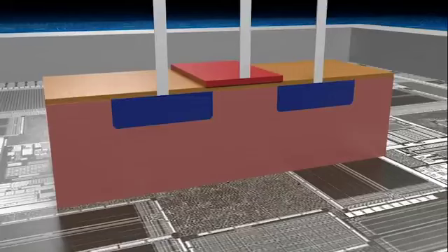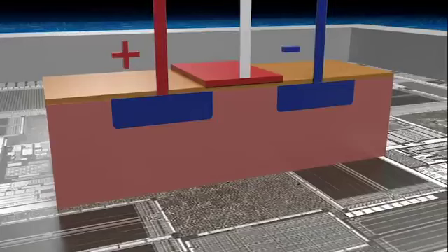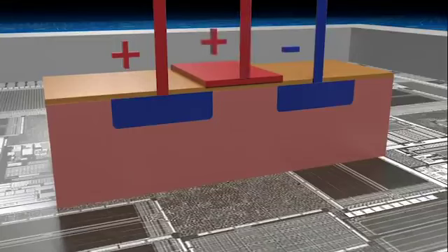If an electrical charge is applied to only the 2 outer terminals, electricity cannot flow as the transistor is blocked. This changes, however, if an additional charge is applied to the middle terminal. Electrons from the p layer are then pulled toward the middle terminal and accumulate at the area bordering the silicon crystal and the insulating gate oxide.